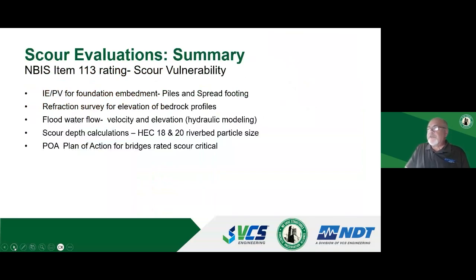That means the spread footing embedment or the pile length and the changes of those, or if the piles have been compromised, the debris could impact timber piles and threaten them. Refraction survey, as a proactive measure, can determine where the elevation is of the rock, and if the abutments are founded on rock, they are probably less vulnerable.